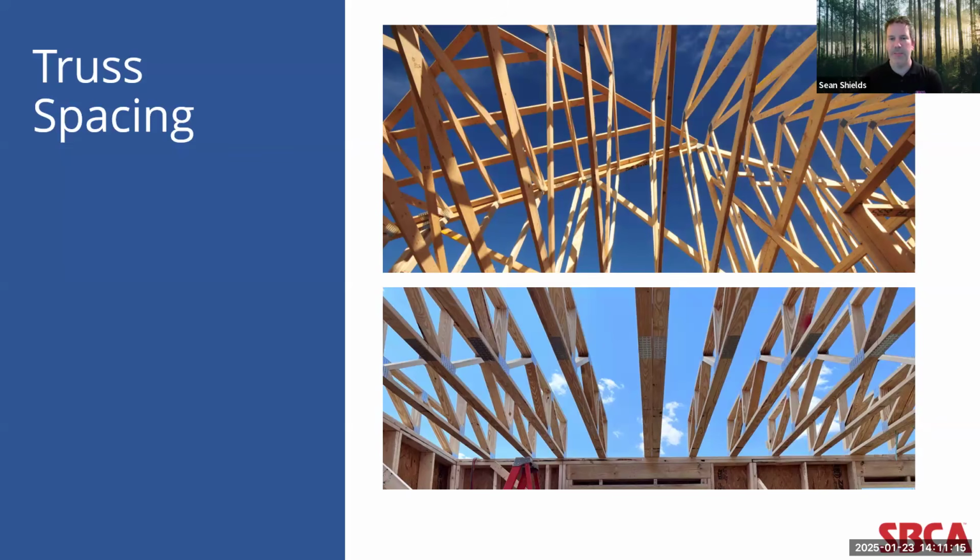Sometimes, if it's anticipated there will be something like slate or concrete tiles on the roof, so again, very heavy dead loads, the roof trusses may be spaced 12 inches or 16 inches on center instead of 24. Similarly, floor trusses can be spaced 12 inches or sometimes 19.2 inches on center instead of 24 inches on center when the building designer wants to achieve, let's say, a longer span at a given floor depth, or if they want to control for something like floor stiffness.